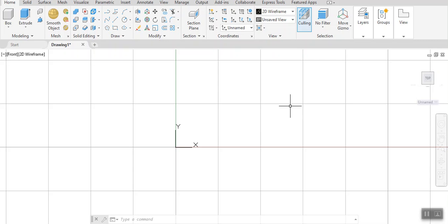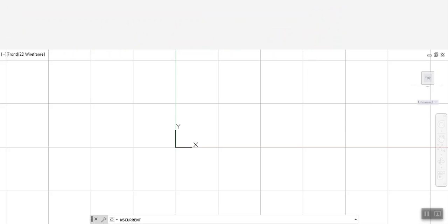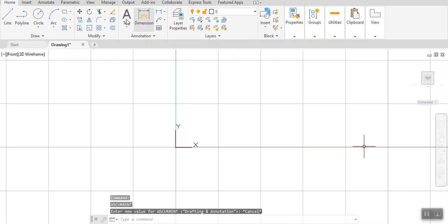This is going to be a two-dimensional drawing initially, before it becomes a 3D drawing. So I am setting my menu, moving my cursor over. There is a picture icon of a gear here, and there is an arrow next to the workspace switching. Workspace is the name of the menu, and I click on it and choose the Drafting and Annotation workspace. My screen on the top, on the ribbon, totally changed.